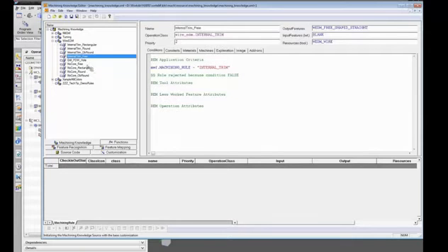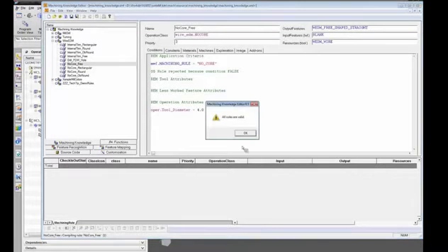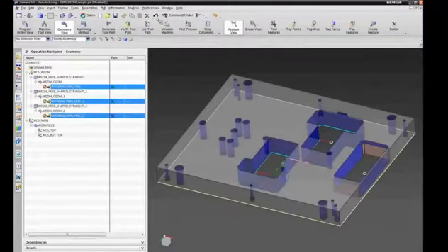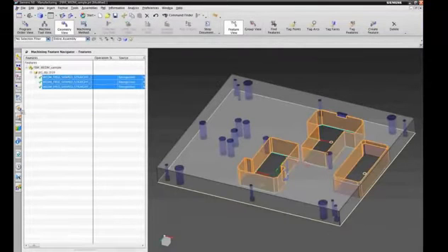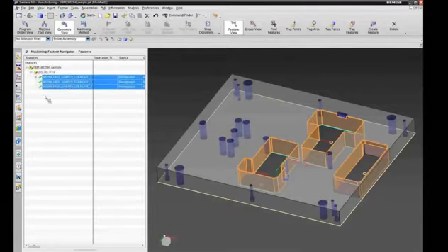And I see two operations here, two rules for my WireEDM FreeShape feature type. One is internal trim, and the other is no core. And I see that the no core has a lower priority value, so it's an alternative that's not being used. If I would change that priority, save my best practice rules, and just undo my results here, so that I just have the features and no operations anymore.